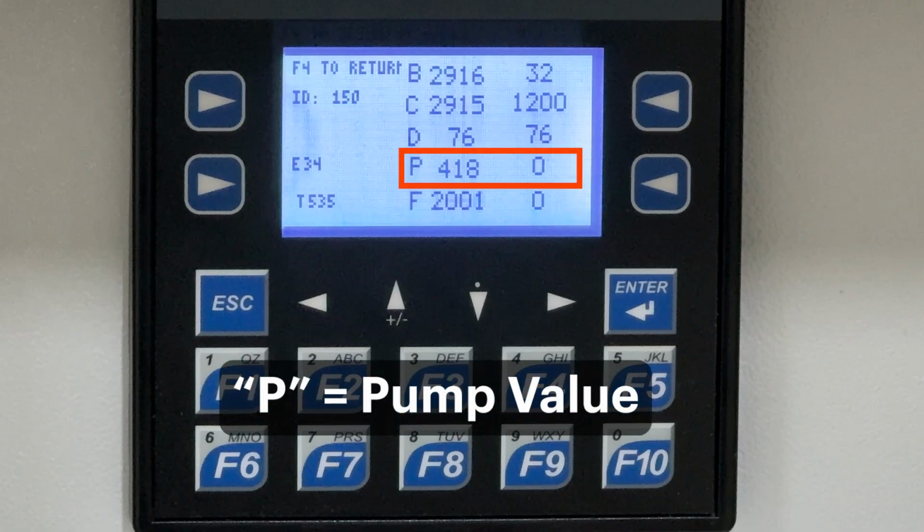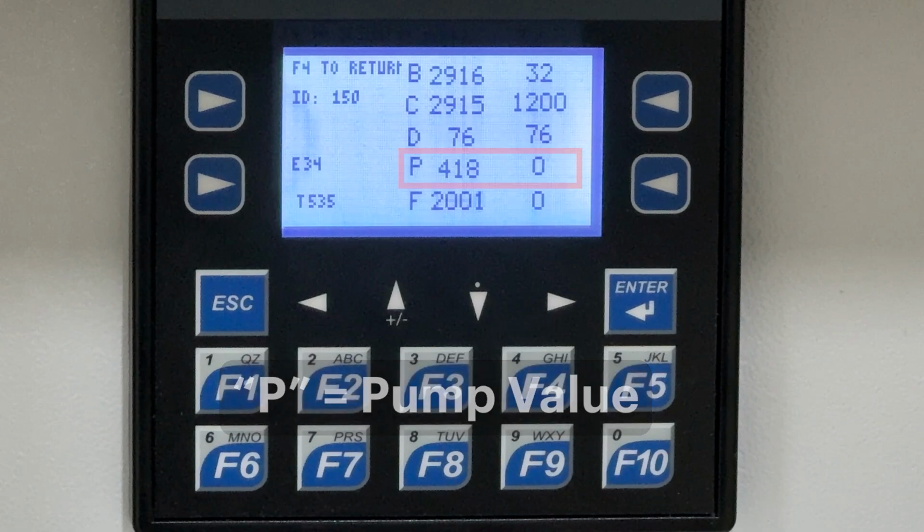P stands for pump value and represents the amount of voltage being delivered to the pump. This value is automatically adjusted in the software in real time to achieve the flow target stored in memory. Nominal P values vary depending on the pump revision installed.